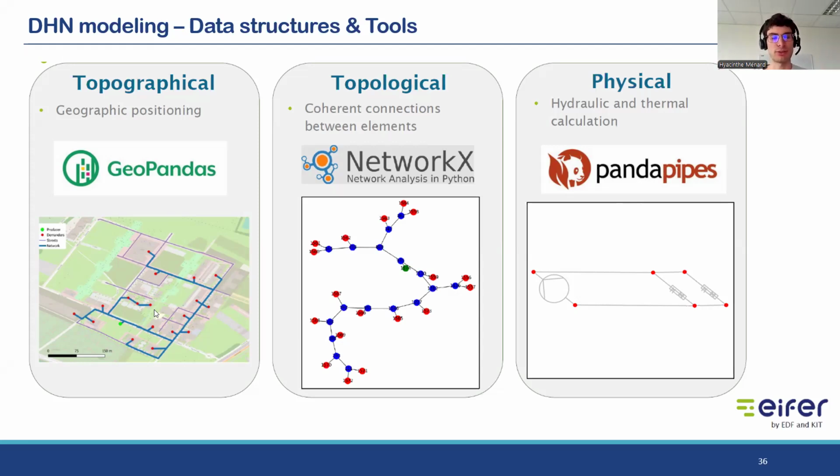They are both at the same location. But for pandapipes, I need to model both, because I actually want to model a loop of water in my network. And then I have to include the models from the available pandapipes component library for the heat plant and for the substations, but I will detail that just later.